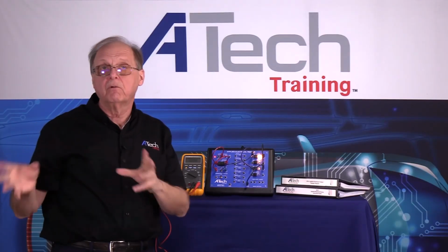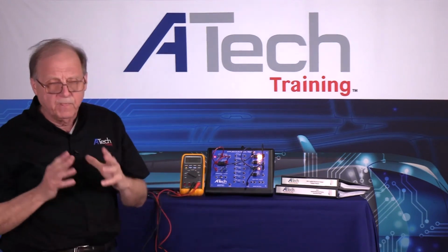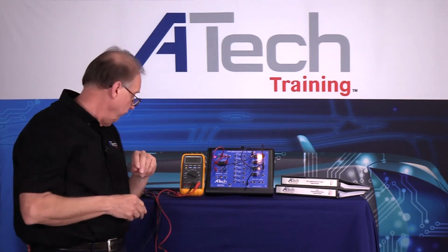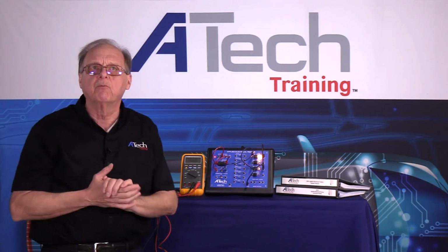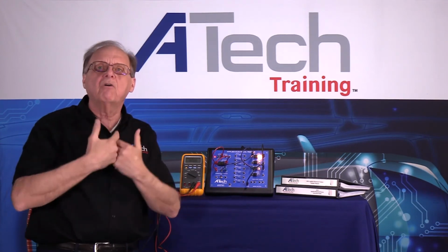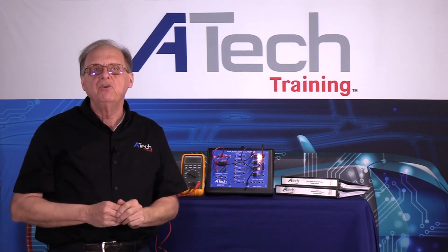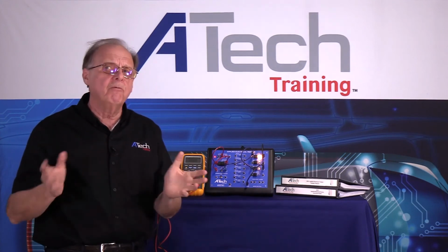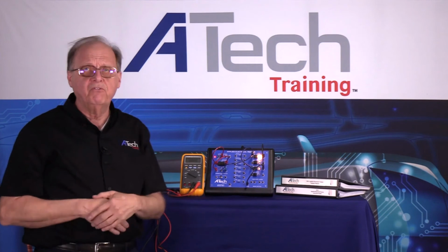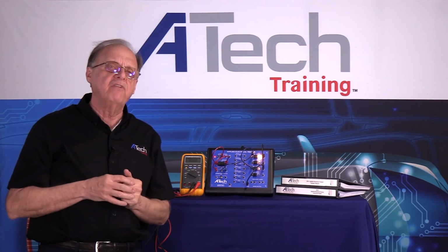I can have two dissimilar readings on it, and they will learn the math and the procedures. The other thing is, you have to keep this in mind, it's a lot of fun playing with students. And one of the things I like doing with them is, if you're looking at a student having some problems with it, you want them to calculate the resistance in the circuit, key on, off, resistance, because there should be no voltage in the circuit. Then you want them to fire it up and calculate at the 14 volts, whatever feed, calculate the amperage. Well, there's a problem with that, because when that bulb lights up, it changes resistance. So that's the only exception I found to Ohm's law. And you have to teach that to your students.